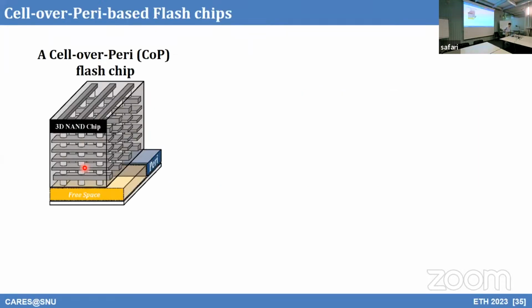Our main motivation was that when we go up in 3D flash memory in the vertical direction, and people tried, it is actually now in commercial products too. In order to sense cells' voltage level and also send data out of the chip, there are peripheral circuits that take about 20% of the cell area.